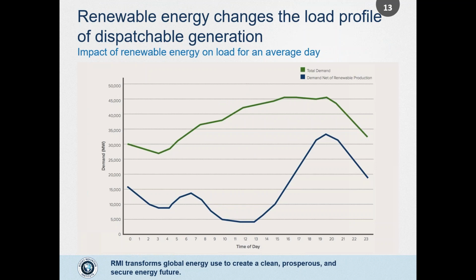And so this chart shows the impact that wind and solar have on total demand throughout a day in our forecast. So as you can see, this blue curve over here, that's our net load, which is our load without solar and wind generation. And this, as you can see, bellies out around midday and then quickly ramps up in the afternoon hours, hitting its peak between about 6 and 8 p.m. Many folks are probably familiar with the term the duck curve. This is exactly what it's showing.